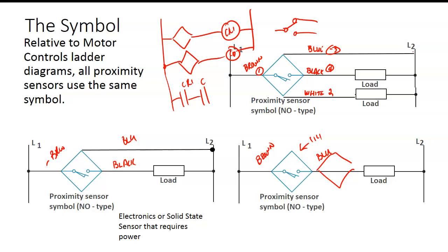We had an electronic scale out in Opelika where the printer wouldn't work. And we'd get down there and we noticed when a person stood in front of the window, it worked. When the person moved away, it didn't. What was happening was it had a photoelectric sensor and the sunlight was getting into it. So we figured that out. So how did they fix that one? We came in and took an input that they didn't hook up, and connected it to the other one. We hooked it up to, I can't remember if it was a positive or negative.